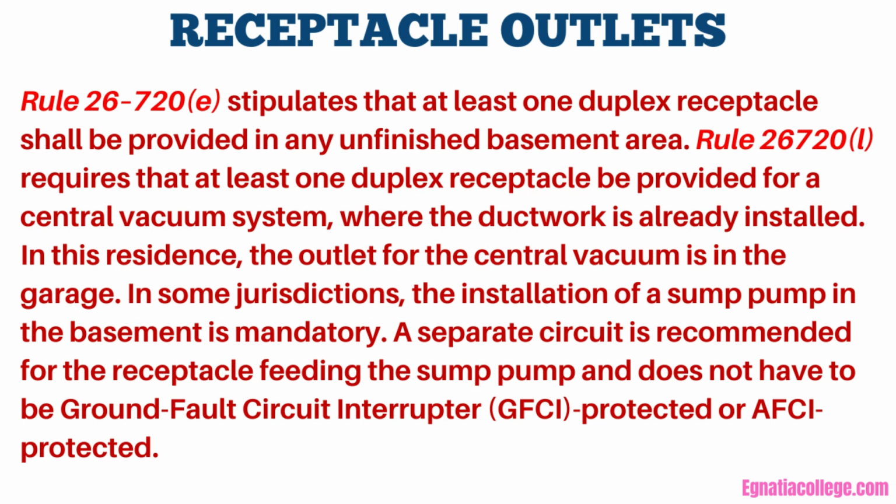In some jurisdictions, the installation of a sump pump in the basement is mandatory. A separate circuit is recommended for the receptacle feeding the sump pump and does not have to be ground fault circuit interrupter (GFCI) protected or AFCI protected.